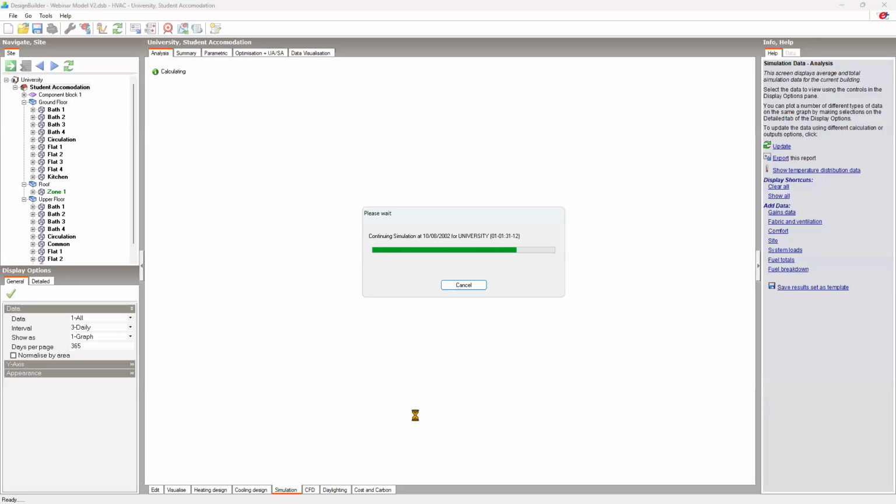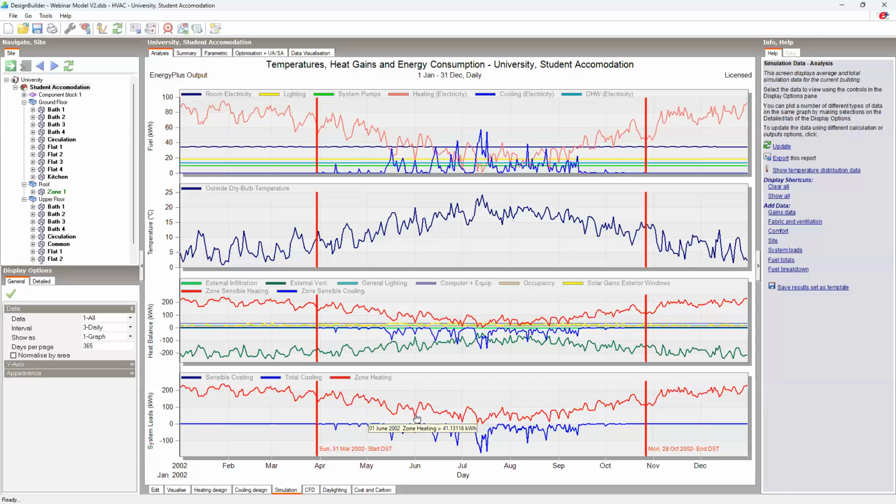I have skipped this to save time, but the type of QA checks you can do is by simulating short time periods at high time frequency, like hourly or sub-hourly, to ensure that the systems and operations are running as they should. This type of QA checking and sanity checking is a very essential step for modeling.